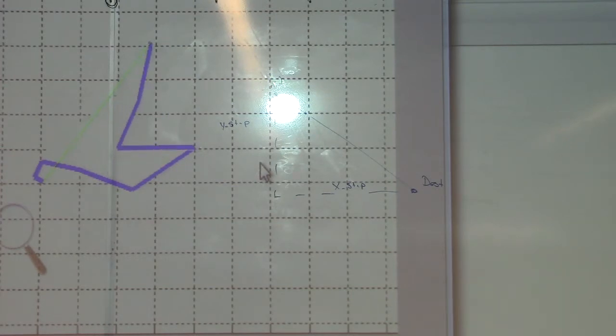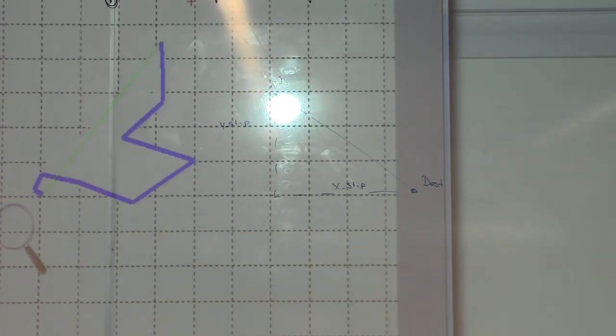As we get closer and closer up there, you notice that it's slowing down. That's because it's having to make more and more corrections in order to perform the CCD algorithm. Each time it's moving towards that point, it's having to adjust the base joint here, which means it has to go through and redo all of the calculations at least once.